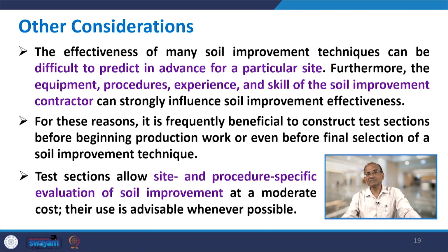For these reasons, it is frequently beneficial to construct test sections before beginning production work, or even before final selection of a soil improvement technique. Test sections allow site and project specific evaluation of soil improvement at a moderate cost. Their use is advisable whenever possible.